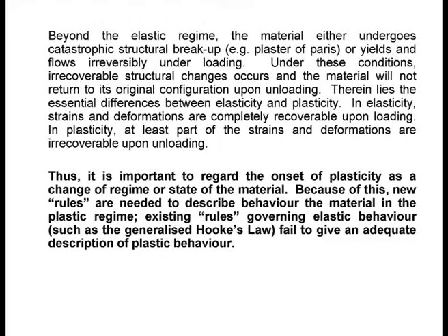We need to regard it essentially as a change of state or change of regime of material behavior. Because of that, you need some new rules to define plastic behavior. The existing rule that we learned yesterday, the generalized Hooke's law and all those stress and strain proportionality, works very well with elastic material, but it doesn't work with plastic material. So you need new rules, and the new rules, at first sight, are actually less intuitive.